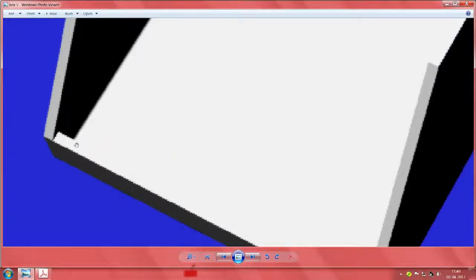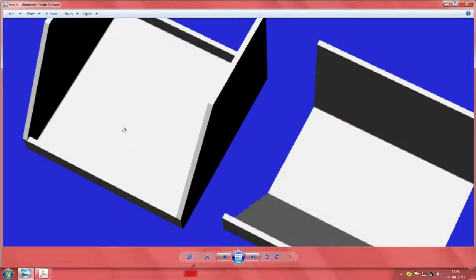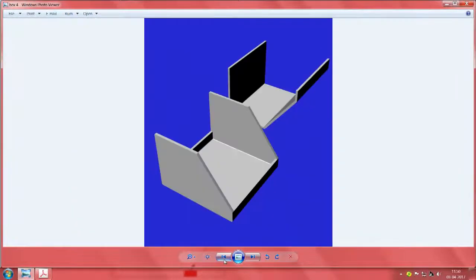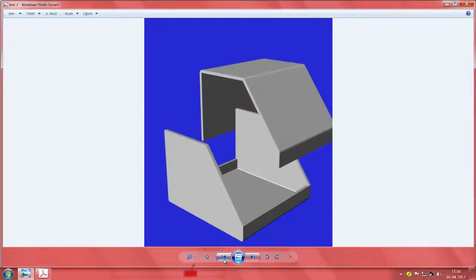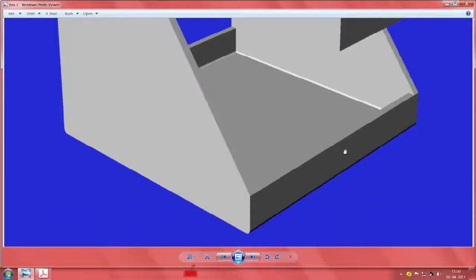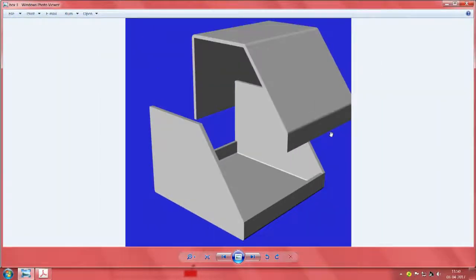2 or 3 small things have happened. One of them is, is it possible to fabricate a piece like this where the internal dimension from here to here should be exactly equivalent to the limb dimension here? 2 issues are there. One is, if we take that this cover is overlapping on the other, I think the next picture shows you those things. So, if it is overlapping like this, you need to very carefully calculate various dimensions here.